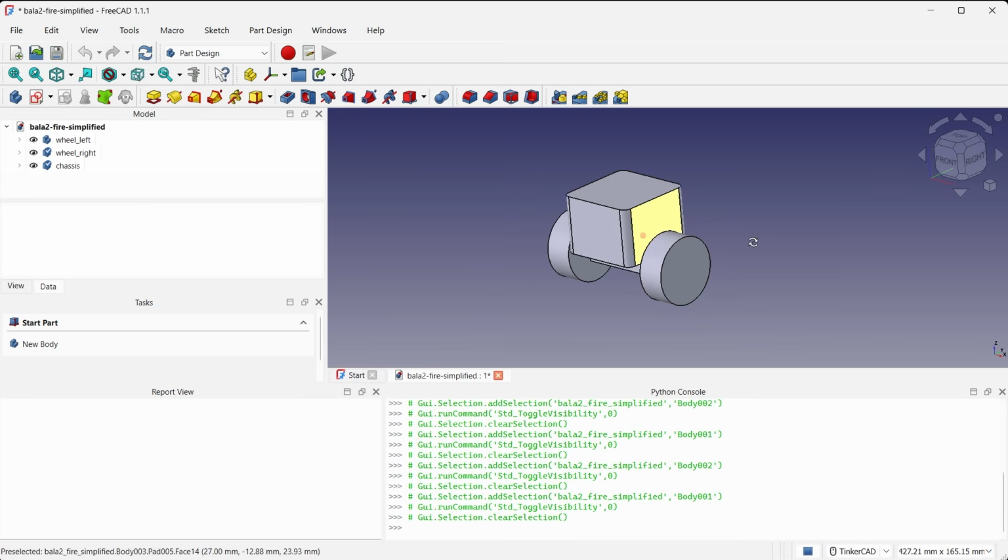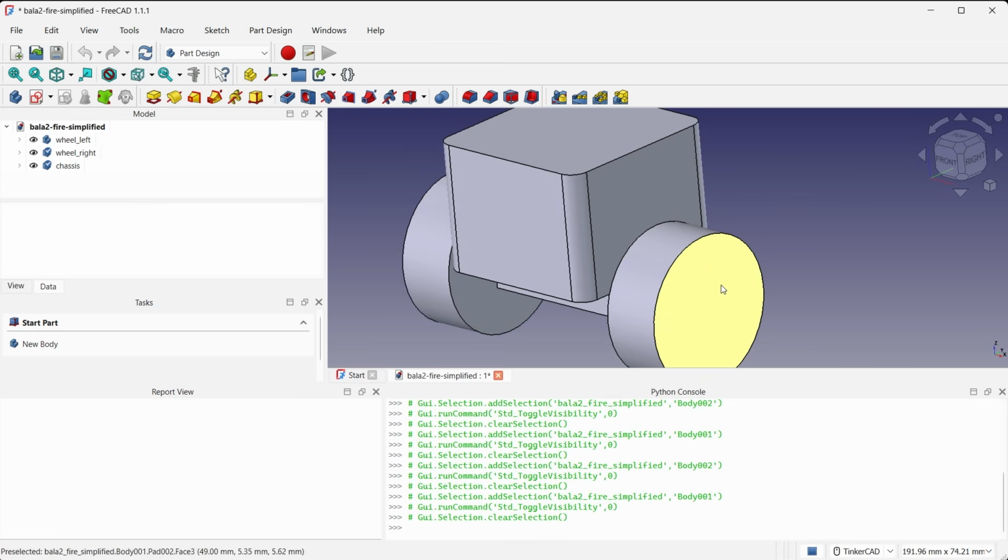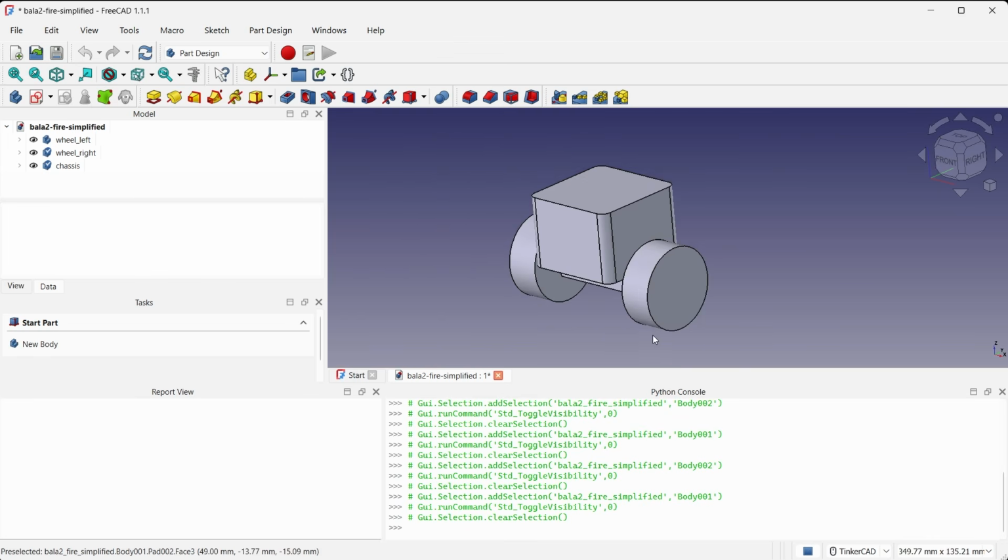But once again, that's going to very much increase your computational complexity. So to keep this simple, we're going to assume a smooth wheel, and we're just going to play with the amount of friction that this wheel has on the ground to simulate something like the ridges. So this is one of those sim-to-real gaps you're going to run into with MuJoCo, especially if you're using a very simple model like this for your robot.